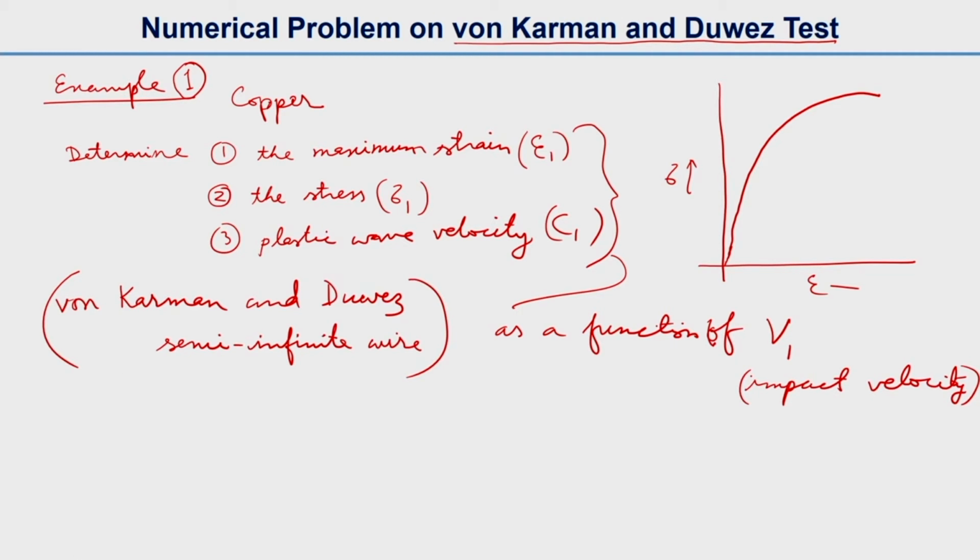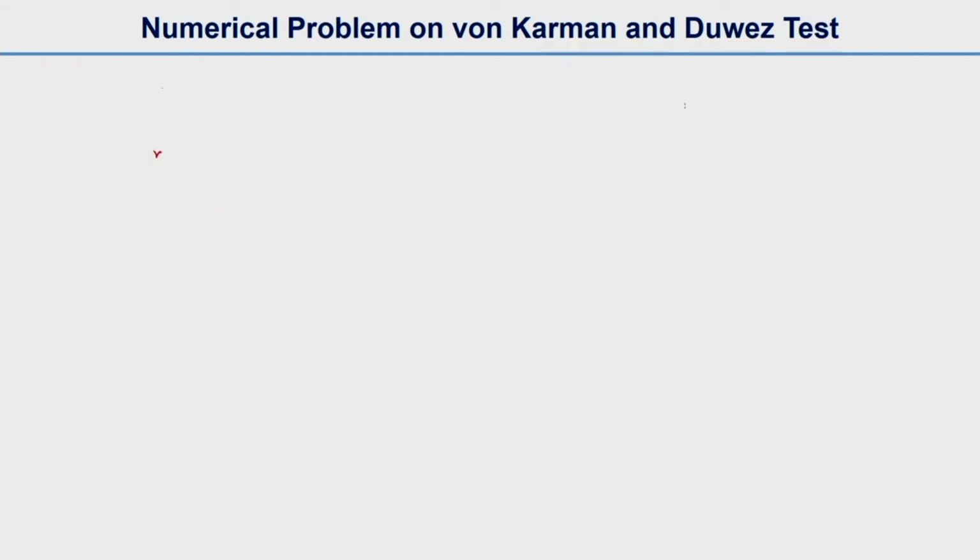So we have the stress strain curve. From there, as we know, for the plastically deformed part we have the relationship sigma equals k epsilon to the power n. So what we can do is plot that in the logarithmic scale, and that will be the natural logarithm of sigma equals log k plus n log epsilon, and we will plot it here.